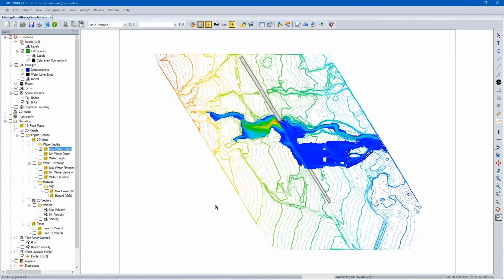And that's something that we really don't want, because in this case, as we looked at when I loaded the drawing file, we want to begin to put a new set of lanes going north just to the east of the existing road. So we're going to have to identify what we can do about this in that new design condition. We could probably coordinate sags and things like that, but this is a good arterial, and we want to make sure and maintain this at this flood event, because there's been a lot of upstream development here.